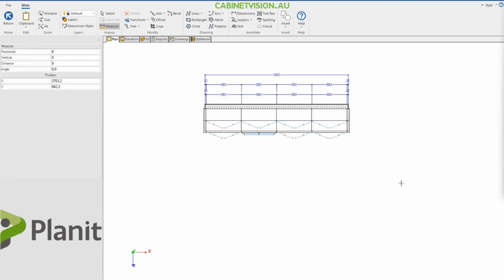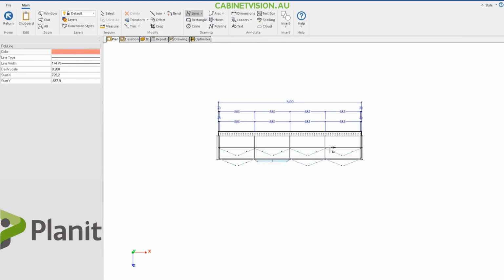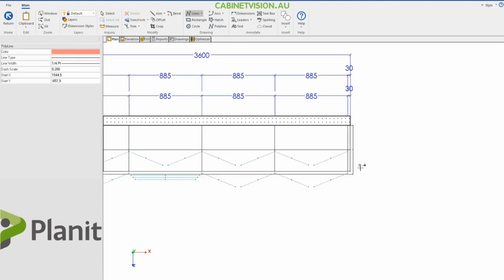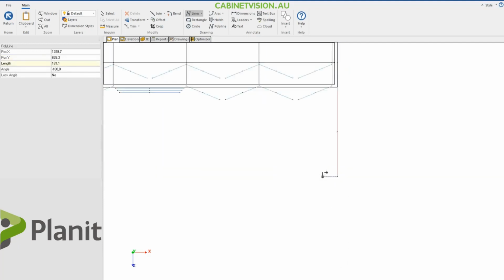Another way that the 2D CAD can help us is by giving us the ability to measure out like a draft. For example, using the chain tool will help me to measure out exactly where I would want to place an island bench or a reception desk on my page. So, if we did that together, I can use my chained line tool, and it's still pink, fantastic. And now I know that my counter is currently 600 mil deep. So let's say I would like to have a 1100 mil gap, length, 1100 mil gap.